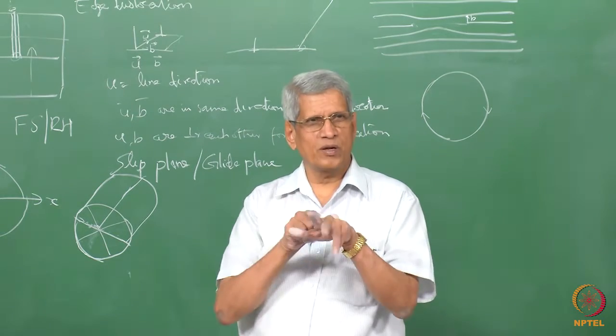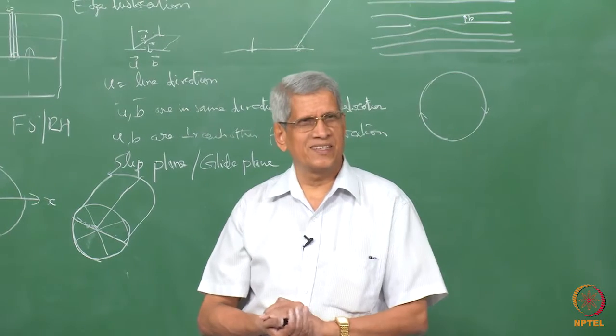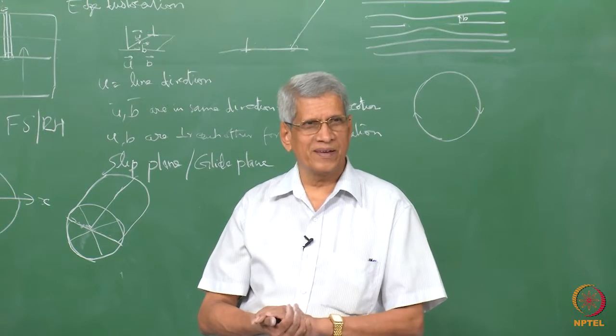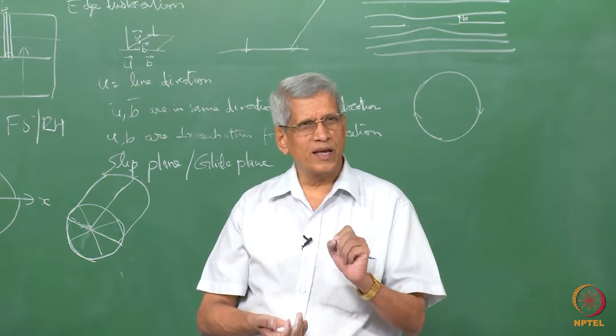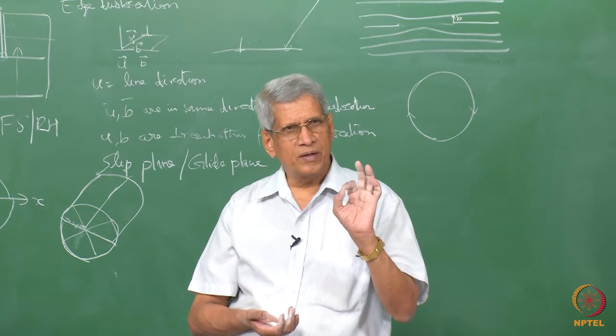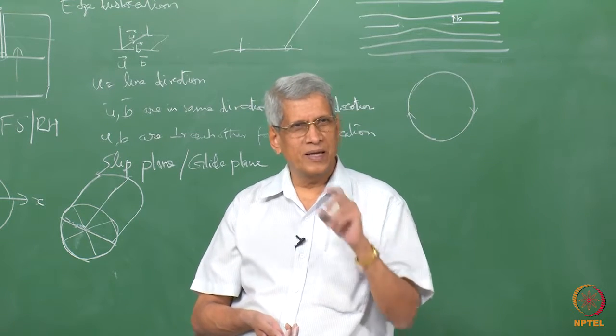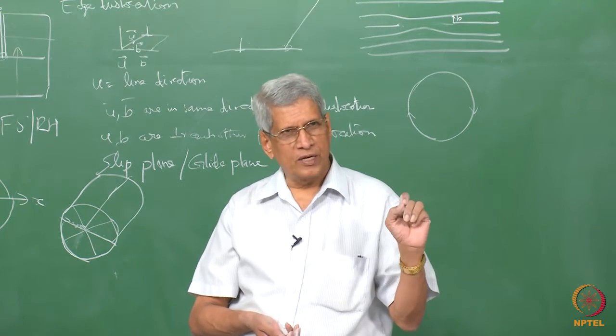We said that some dislocation is there, some cut surface we are looking at. Where it starts and where it ends is very important. The dislocation can never start within the center of the sample. It has to always be from outside.